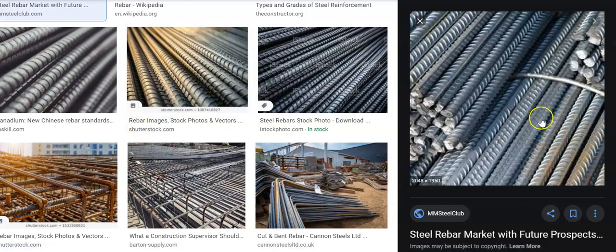Why do you think the texture is rough? So that as the concrete sets and hardens, it sits between these little raised edges. As the concrete dries and gets hard, it holds tightly onto the bar. If the column or the beam wants to bend, and the concrete was unable to hold on to the bar, the bar would just slip inside. It would move freely inside the concrete.